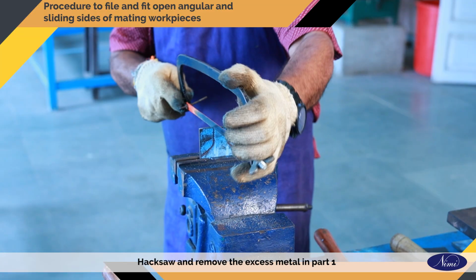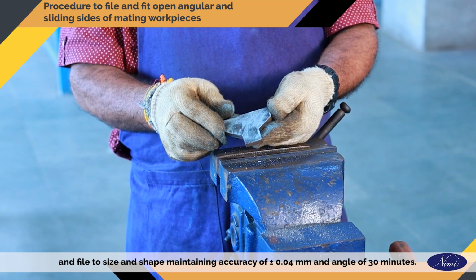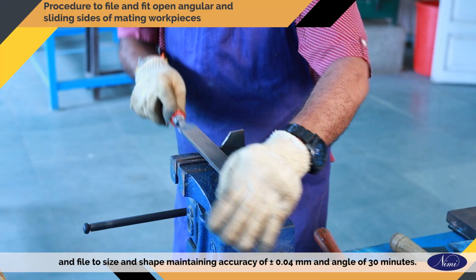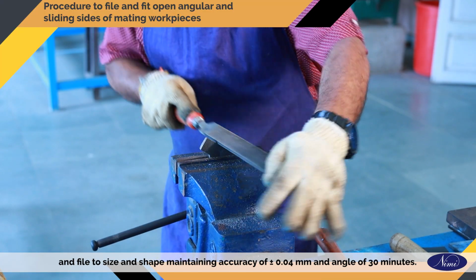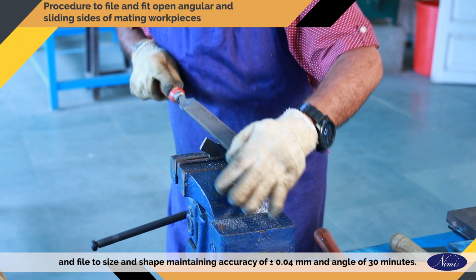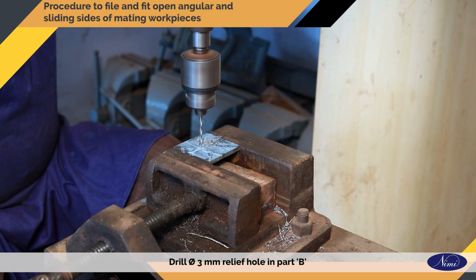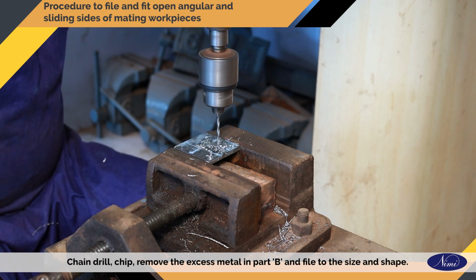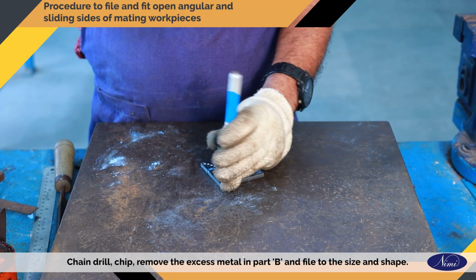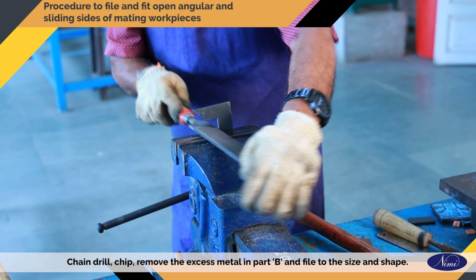Hacksaw and remove the excess metal in part 1 and file to size and shape, maintaining accuracy of plus or minus 0.04 mm and angle of 30 minutes. Drill diameter 3 mm relief hole in part B. Chain drill. Chip, remove the excess metal in part B and file to the size and shape.